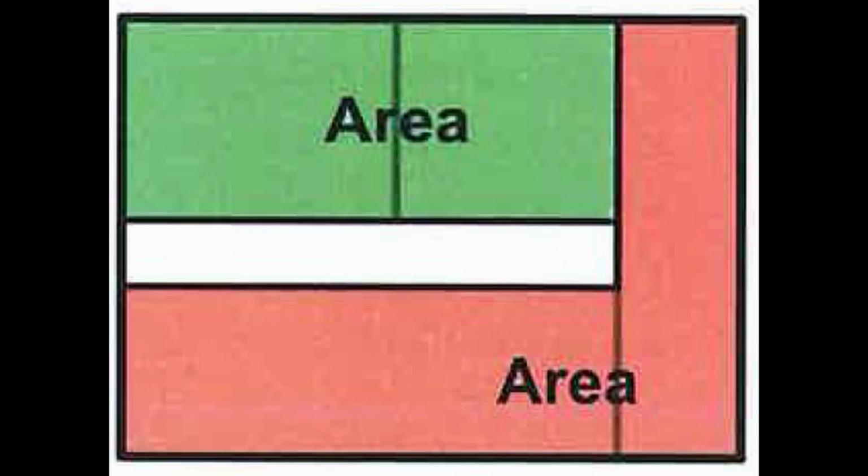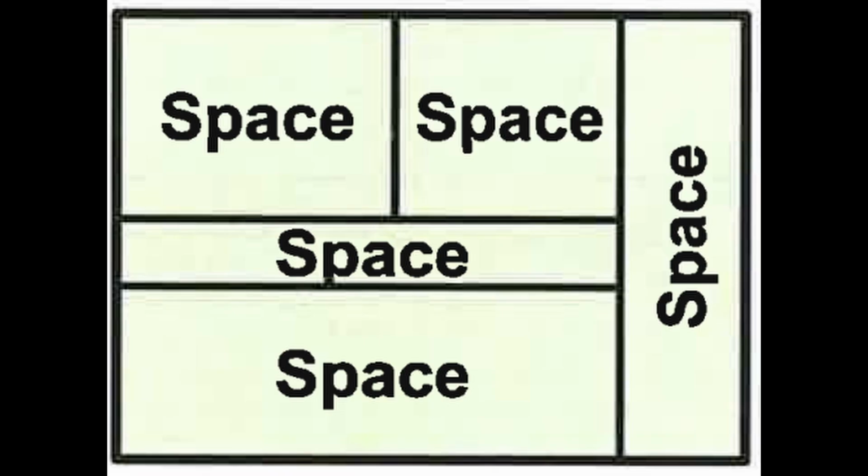Areas are also architectural, but they work at a broader level. They're used in area plans to analyze departments, circulation ratios, rentable space, or apartment sizes. Spaces, however, are the MEP equivalent of rooms. They use the same bounding elements, but they store mechanical and electrical data, things like air change rates, temperature, humidity, lighting loads, and power density.